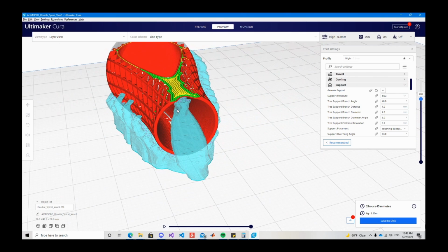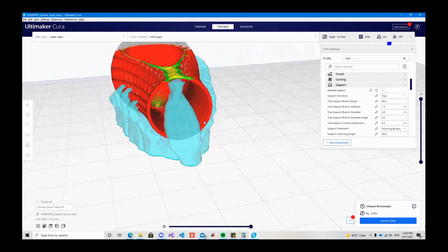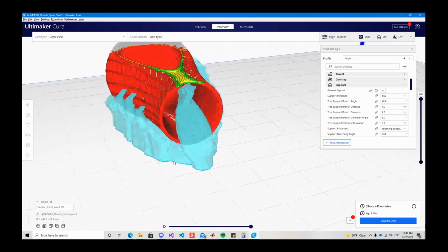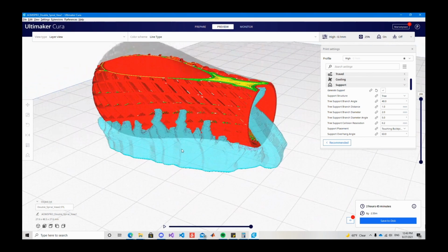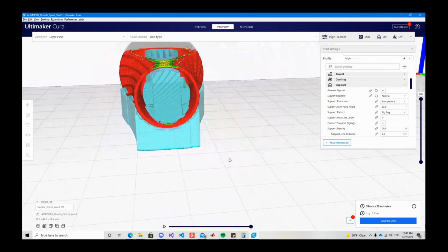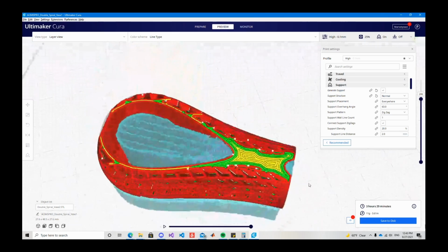So as soon as the filament gets cooled, it doesn't deform in the air, and you don't get a weird print that has a dent or a dive in it. Tree supports are the strongest ones. You can change it to a normal support, which will just print almost like you're printing another object. It's not really special, but this one has a lot more filament on the inside.